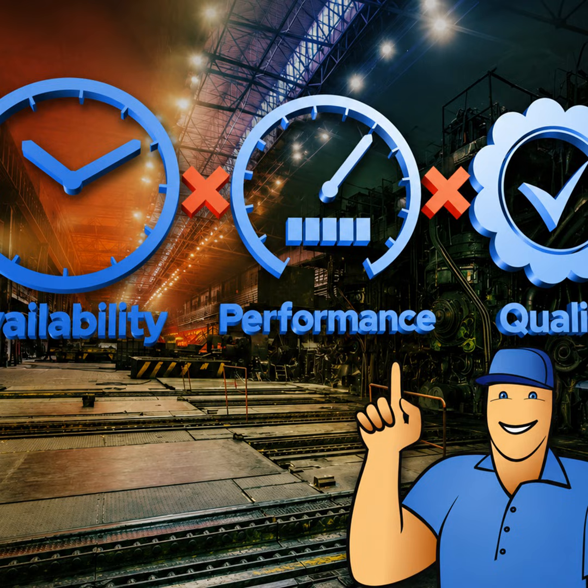Now, you need to calculate how fast your equipment was running. According to the design specs, the ideal cycle time is 2 minutes. That means you could potentially produce 232.5 units during your 465 minutes of runtime. However, the machine actually produced 204 parts.